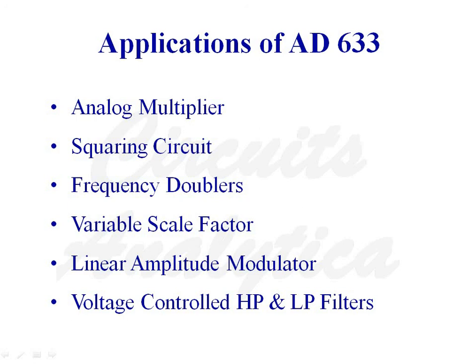Applications of AD633. AD633 can be used as a squaring circuit, analog multiplier, frequency doubler, variable scale factor, linear amplitude modulator, voltage controlled high pass and low pass filters.